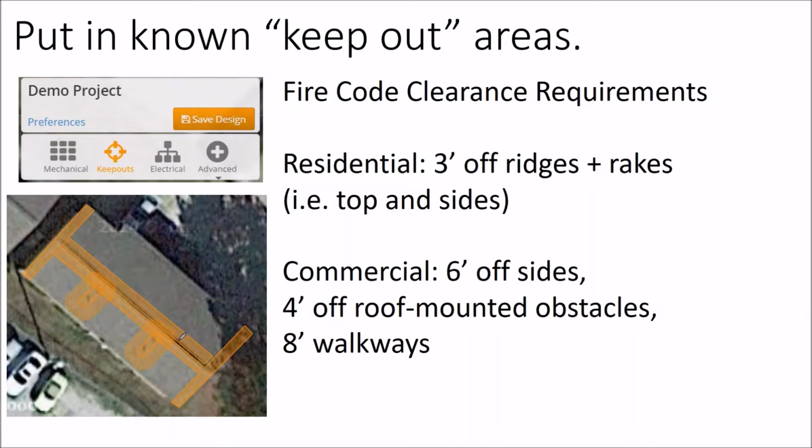The real problem that I find is that even if you're blocking 4 feet on each side from the plumbing vent, if you're putting modules in this area and now your rooftop is a construction site, all of a sudden your keep outs and offsets become walkways. So actually not going all the way up to the plumbing vent but stopping 4 feet short can produce its own set of problems, because it might be encouraging people to walk right next to it during the project rather than otherwise. So you need to talk with your installer about those issues before you get going.